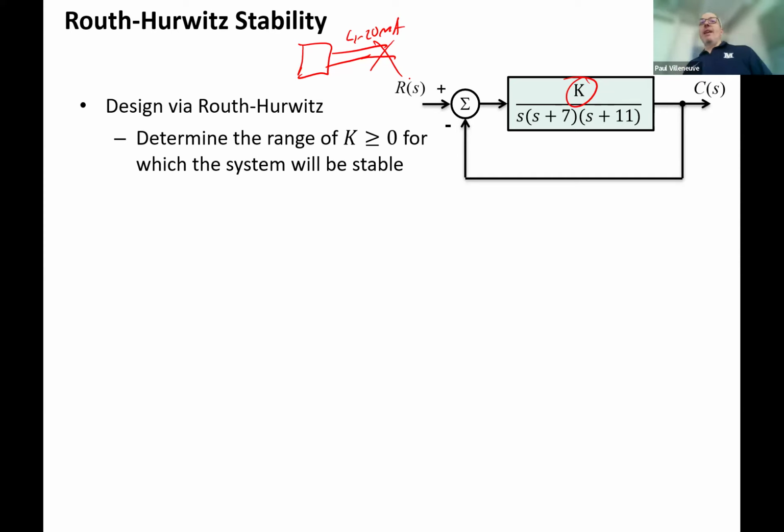So a long time ago, 4 to 20 milliamps is what they did. It's actually kind of a joke, because if you go to an end device, the very first thing they do is put a precision 250 ohm resistor on it to convert the milliamps to a voltage. And then you use your A to D converter to convert that voltage. So all A to D converters have a built-in resistor; you just don't see it. Less voltage drop, yeah, exactly. So there are some advantages for sure to 4 to 20 milliamps.